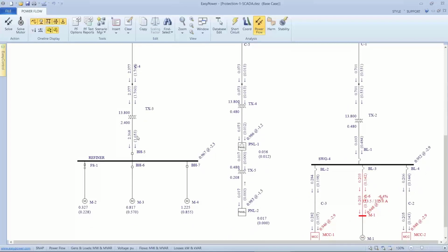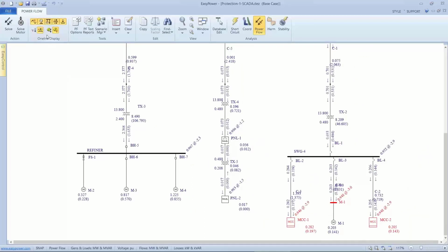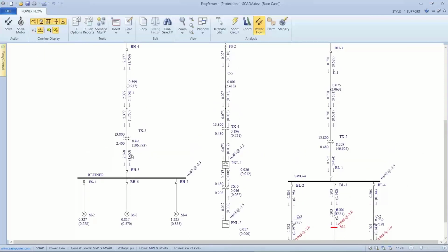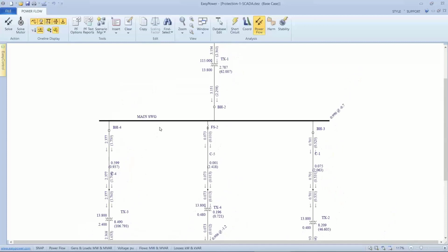Is there anything bad about that? Well, because this is going to be flowing through all the system from the utility to this point, there's losses as a result. And we can see what those are by using this icon here, and we see it's not above a certain threshold. So these are in megawatts and megavars, and the losses are in kilowatts and kilovars. So it's relatively small compared to what the load is actually demanding.